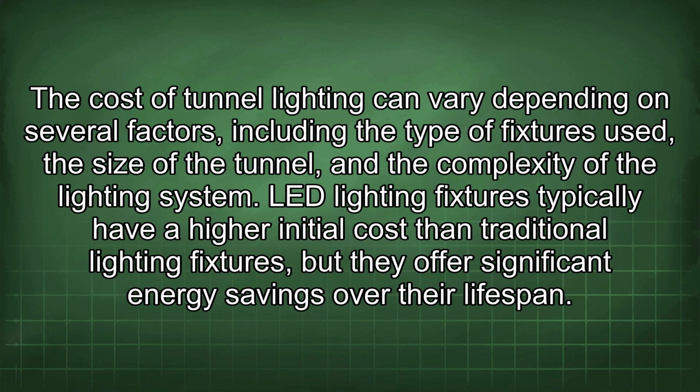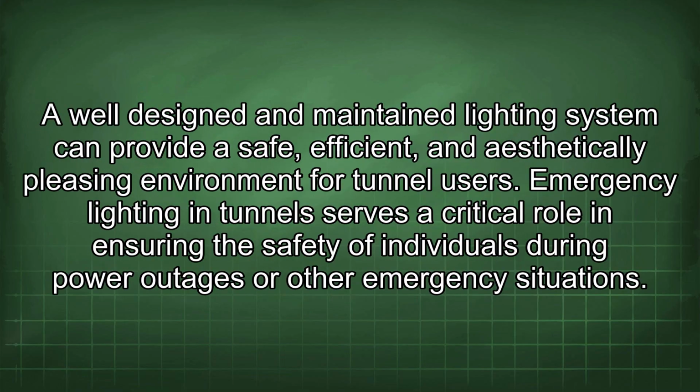The cost of tunnel lighting can vary depending on several factors, including the type of fixtures used, the size of the tunnel, and the complexity of the lighting system. LED lighting fixtures typically have a higher initial cost than traditional lighting fixtures, but they offer significant energy savings over their lifespan. A well-designed and maintained lighting system can provide a safe, efficient, and aesthetically pleasing environment for tunnel users.